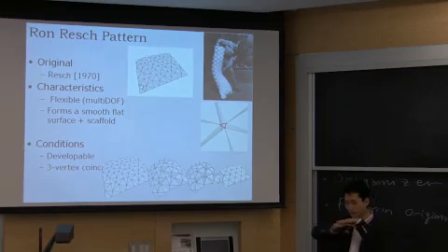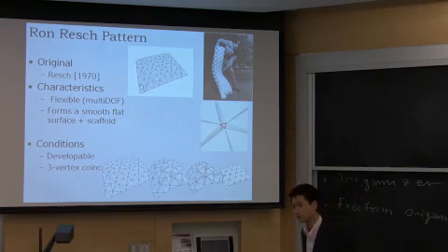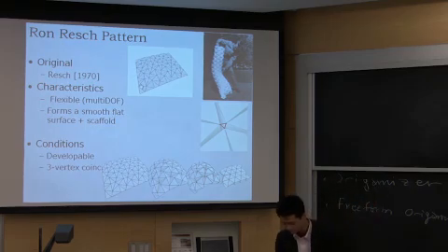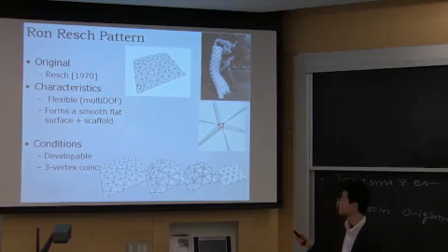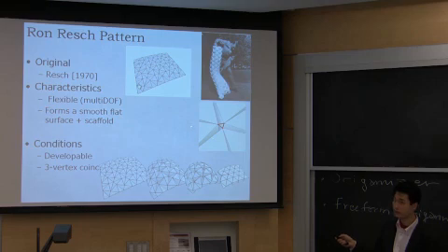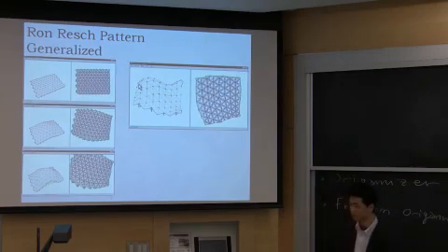So it's composed of a top surface and tucks inside, just like this bunny, but it's more flexible and it can fold from a sheet to the 3D form. In order to design this, we assigned the condition that in 3D state, these three vertices form one vertex. That's an extra constraint to enable generalization of Resch's pattern.